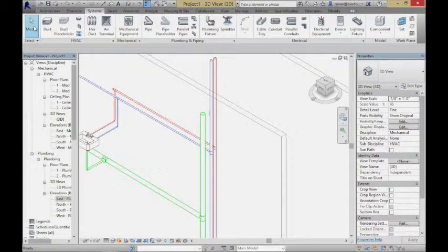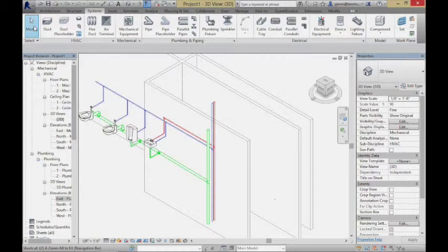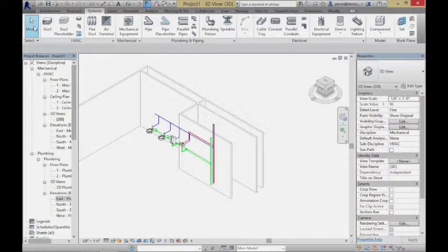So what would I say? A good way to approach this is I would actually start by putting my risers down first as opposed to what I did here. Figure out where the big vertical connections are between the floors. Then figure out where the big laterals are, the big horizontal runs feeding out towards the fixture locations, and then connect the fixtures to the laterals. I think that'll actually be the smoothest way to do that. By doing something like that, we've started to create these different systems that'll all work together.